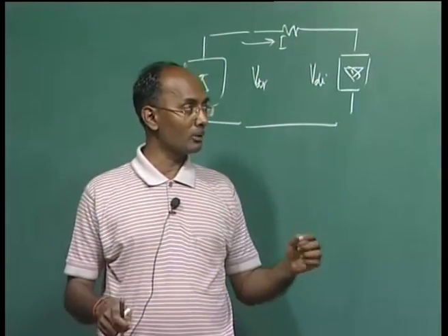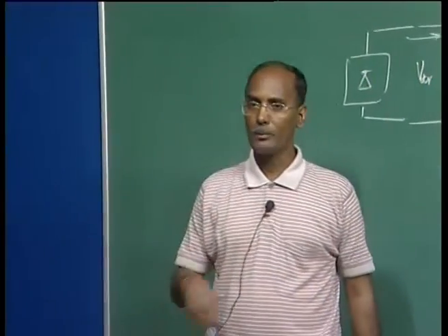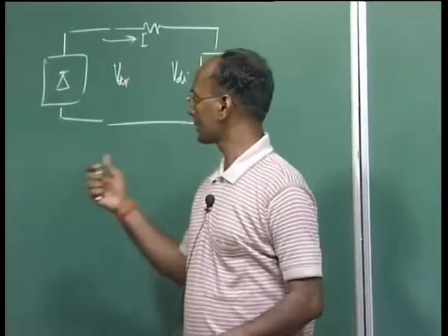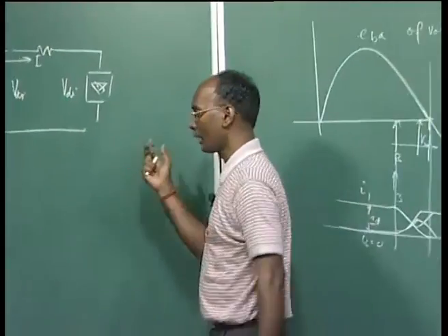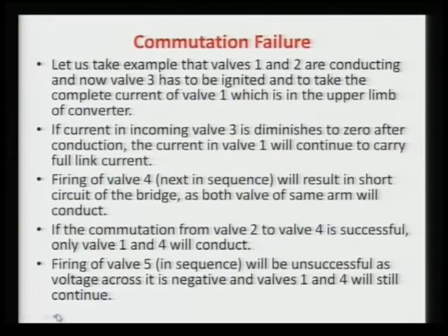In that case, if double commutation failure is frequently occurring, then we have to block the bridge or bypass it. So we will discuss the double commutation failure as well, to understand and see what the output voltage and the sequence will be.